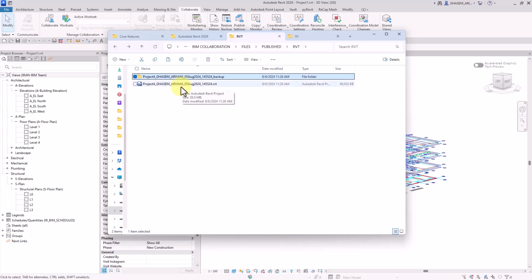In Revit 2026, though, we have no such thing, guys. Basically, this folder, this file has been omitted. In other words, now if we try linking or opening a Worksharing file here, no backup files would be created. As a result, the processes that you would need during your work will go through more rapidly, and also you won't be getting any extra and unnecessary files. In other words, your main file would actually be quite lighter.